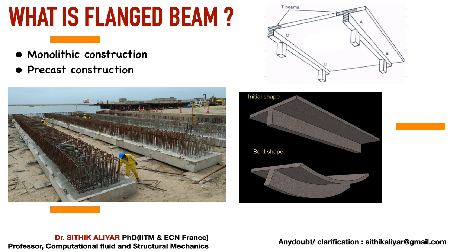Okay, kilonewton meter. So extra, that's the major difference. Again, I will explain at last. Monolithic construction means casting the beam and slab together so that the slab portion will act along with the beam. So some portion of the slab is acting along with the beam.